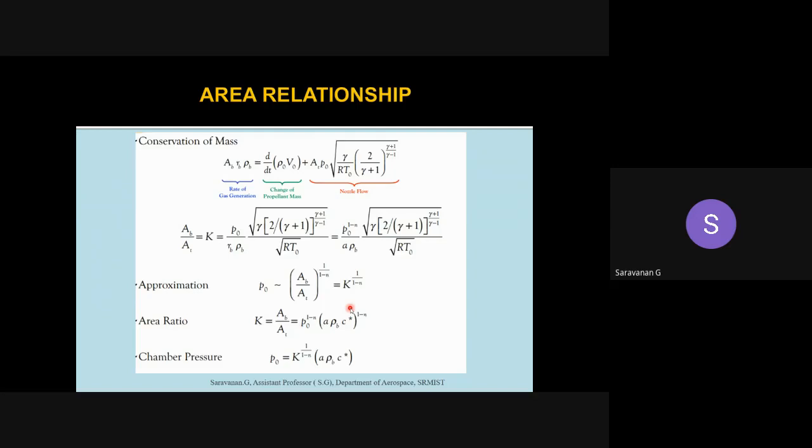So everything depends upon the location. If you want to find Pc at any location, you can use the formula. Ab changes with location, but At is At only; it won't change. The constants are a, the density, and C*, which correspond to the propellant; there are no changes. n will also be given for the particular reaction. The only variables here are burning surface area and pressure. Pressure varies, burning surface area varies. Similarly, if burning surface area varies, pressure will vary.